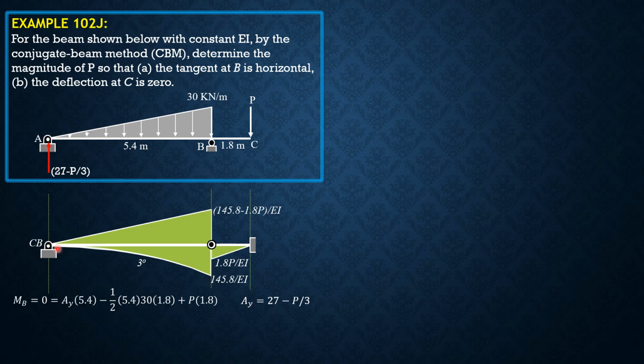Since the portion AB is the only simply supported and determinate portion of the beam, let's consider this first. For positive direction, we have theta B and theta A upward. There's no moment or deflection because these are supports, so therefore no deflection. So we want theta B. In the first part, theta B is 0. So let's have the area upward and this one downward.